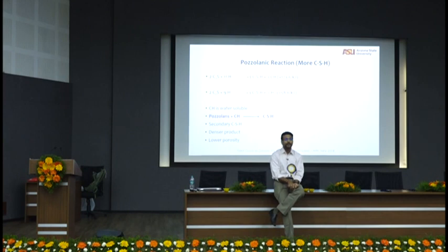I have done, one of my students recently did a work with 85% fly ash and 15% OPC for a 50 megapascal concrete. 90 days, 50 megapascal, 85% fly ash, class F. Possible. Yeah, we had to cheat the system somewhere, and I'll tell you about cheating the hydration system.